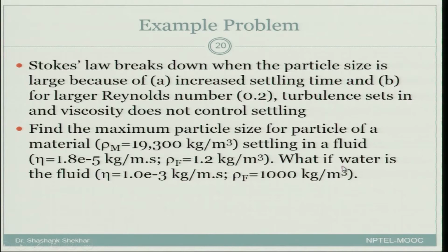So I promised that we will take a look at an example problem based on this, particularly to show that there is an upper size that can be characterized using the sedimentation method. You remember the sedimentation method was based on Stokes law, which says that a falling particle reaches its terminal velocity, and from the terminal velocity you can calculate the distance and the time, and therefore you can say what is the approximate particle size. There was a lower limit, because if the particles are too small, they will remain suspended in the fluid medium, whether it is liquid or gas, and therefore it will never settle, and you cannot calculate the particle size.